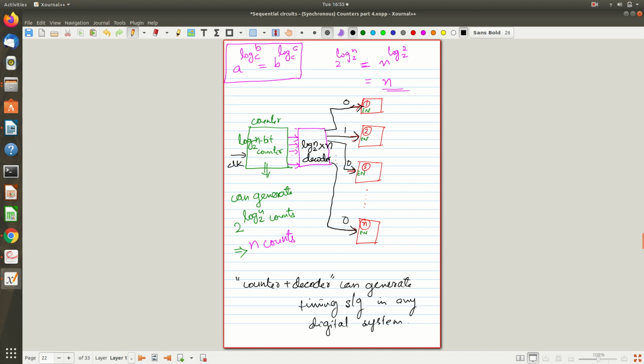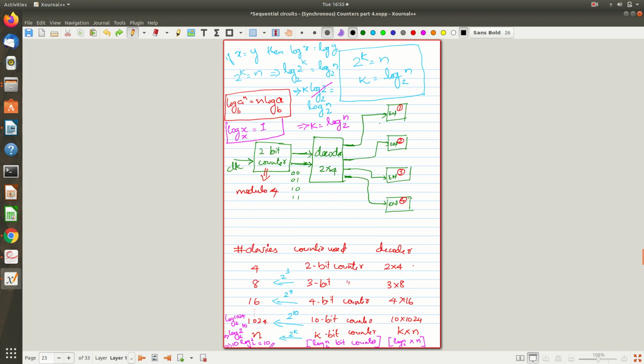So that this alone will be enabled, and then after the third one will be enabled. So something like that is what is needed for me. So I am trying to come up with a different design for that, and it's very easy. You can just implement it using a shift register. Instead of using a counter and decoder, the same thing you can implement using a shift register. So let me tell you how it can be implemented using a shift register.